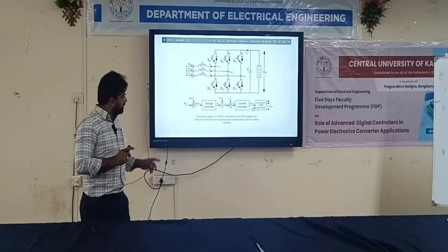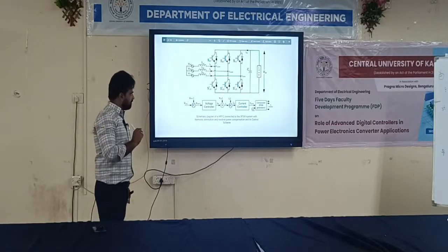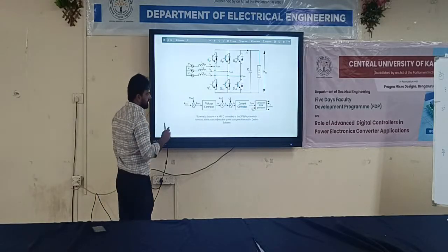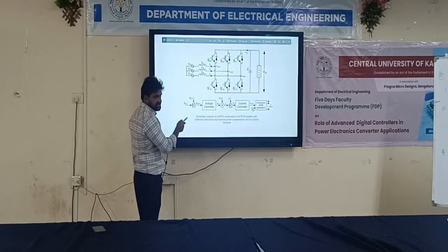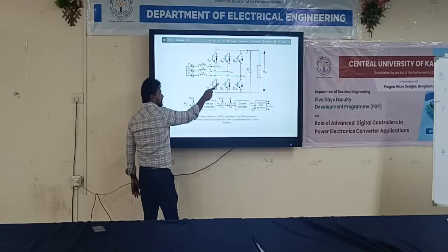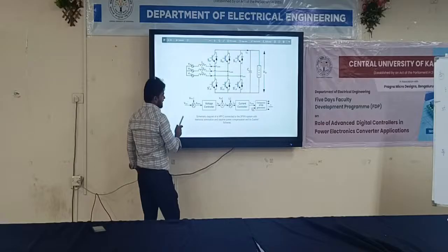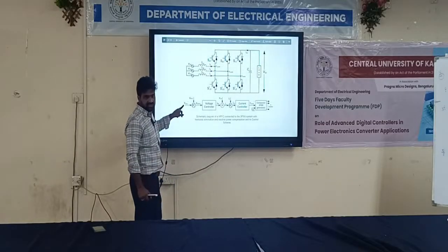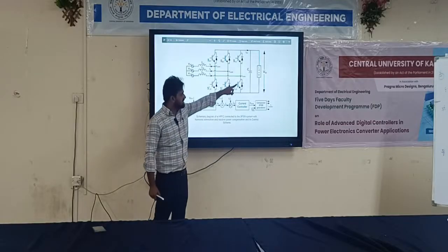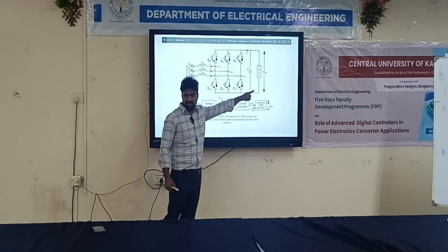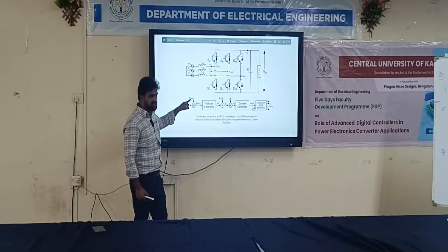First thing, right now we are discussing rectification only. If you keenly observe, it is easy to understand the renewable energy controller concept. Initially, when you want to regulate the DC output voltage, what we do is reference minus actual. Star represents the reference voltage, X represents the phase. In this case, on the DC side, there is no phase concept. So you consider this as VDC star as reference, and the actual.